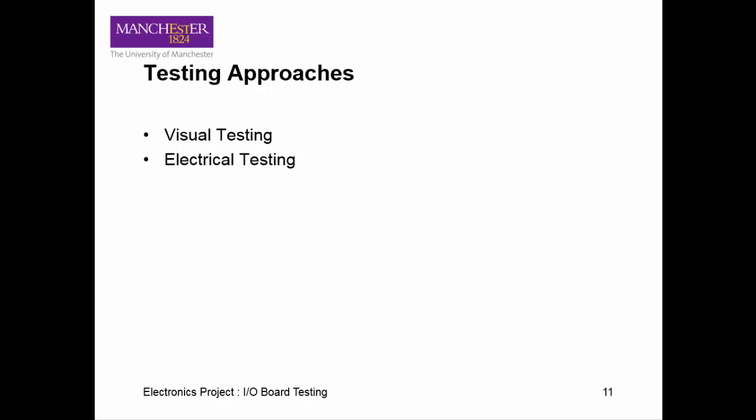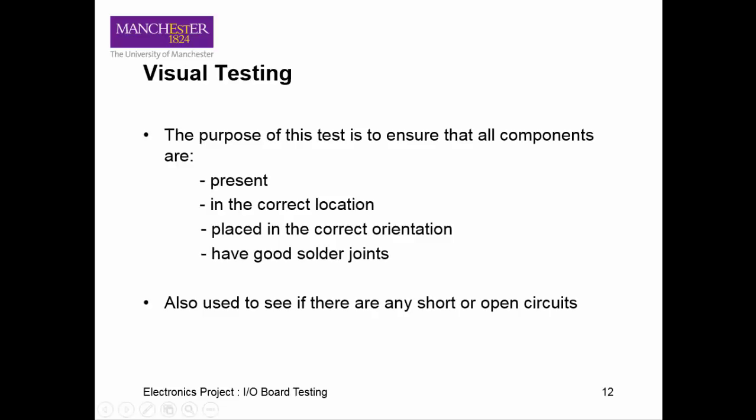Initial testing should be a two-stage approach: visual inspection followed by electrical testing. Visual inspection. Visual inspection is probably the most important test you will conduct, and should be undertaken before any power is supplied to the board. Many faults can be identified visually.